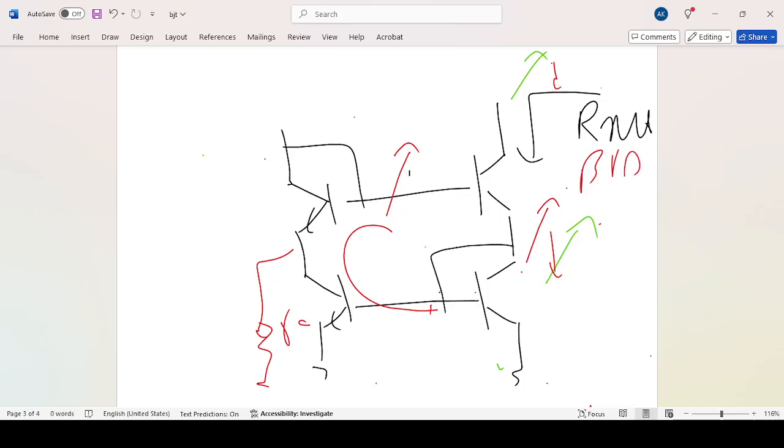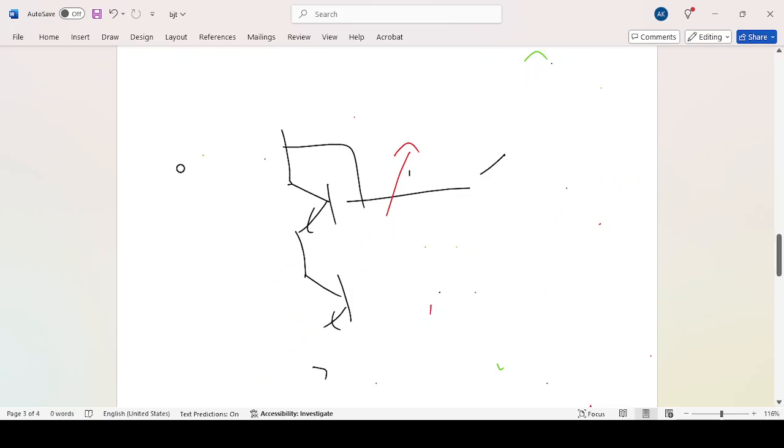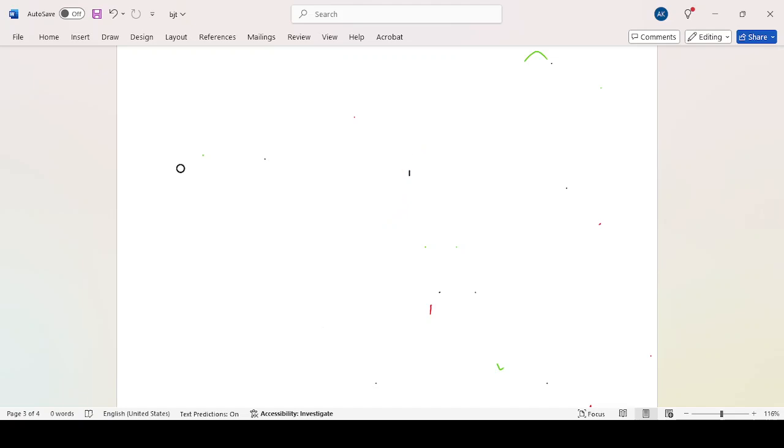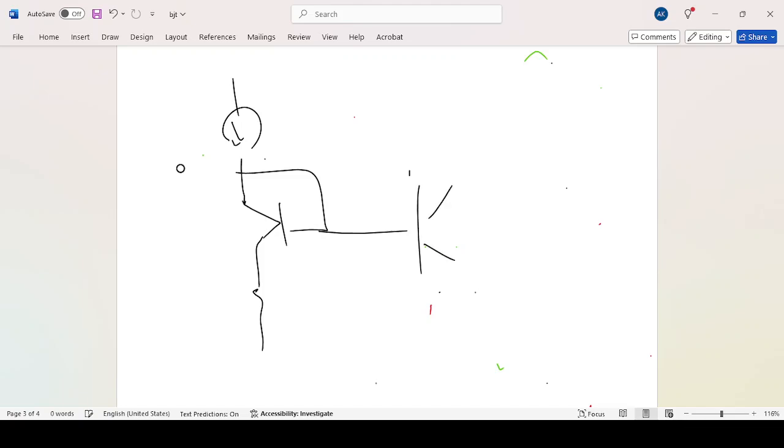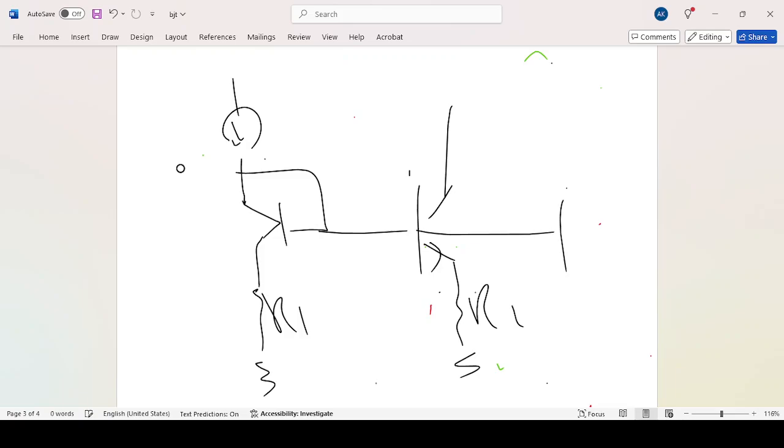This was one thing to mention at the end. Another thing is just the Widlar configuration that is kind of very famous. And in Widlar, one thing that you can do if you have a matching problem is to add a resistor here. And then you can easily copy the signal, called R1, R2, and even you can copy it here.